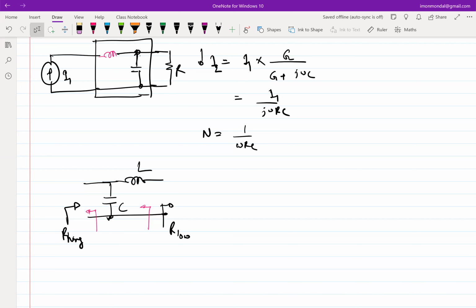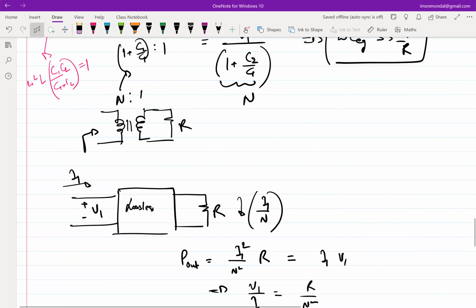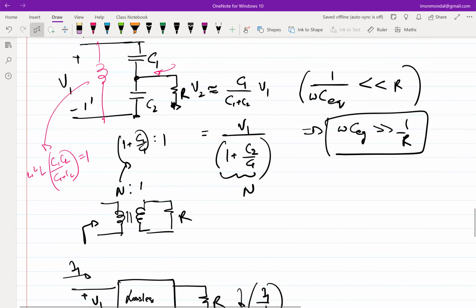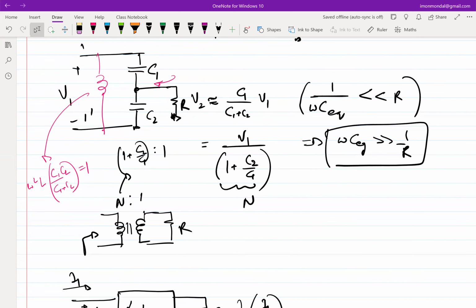Example that you said before. Capacitor divider. There is input R on the top and V on the bottom. So what is being pointed out is that you can flip the same thing here also in this capacitor divider. Just like looking into V1, it seems like you have larger impedance. If you attach a resistance at V1 and look from V2, you should be able to get a lower impedance, right? So anything that you are able to make a transformer with, you can flip the ports and you should be able to get the inverse relationship, right?